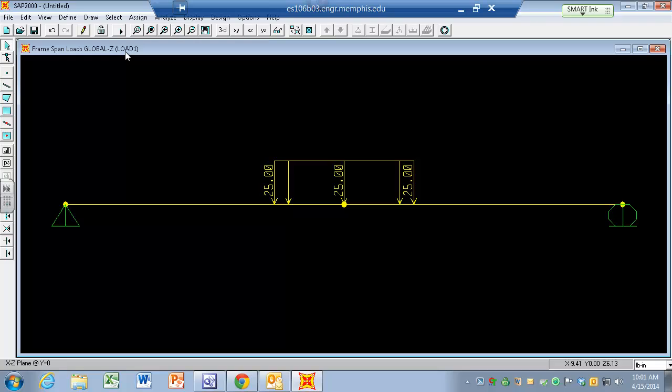By default, it does the first load case, which is load 1. We're not going to do anything for the weight load case because all the loads, unless you say so, consider self-weight. So our weight load case only has self-weight. So later, when we look at the reactions to just the weight load case, that will be actually the weight of the structure.